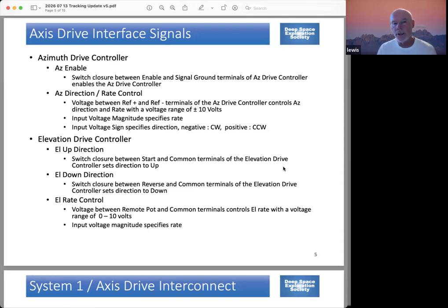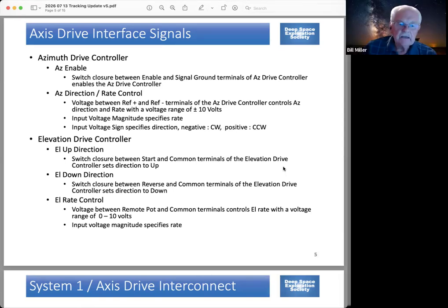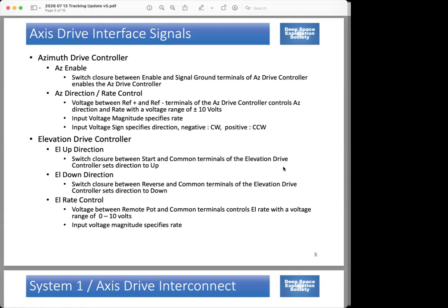That's what the drawings in those two show, but I don't know if there's something not captured. Yeah, I can clarify on that. The VFD opens the main power contactor, and so that turns off both the 480 and I believe it also turns off the 220 to the azimuth, to the Copley. So a better name for that would be on and off.